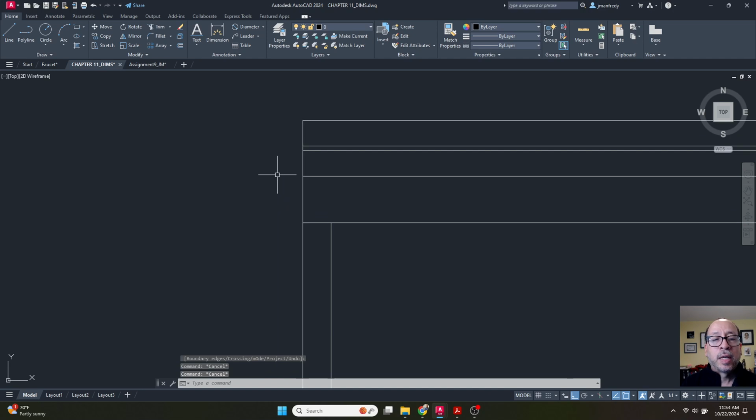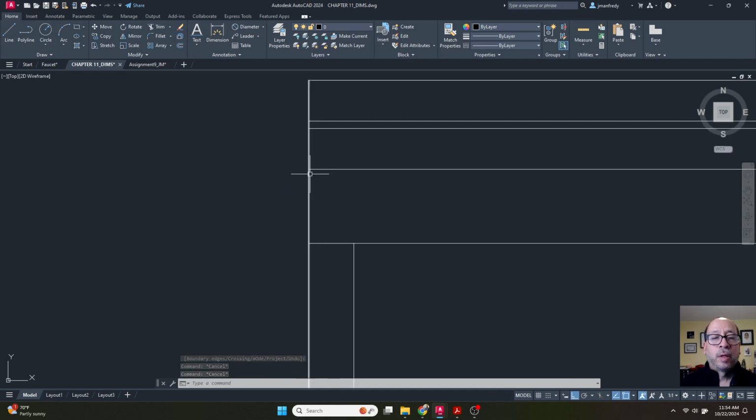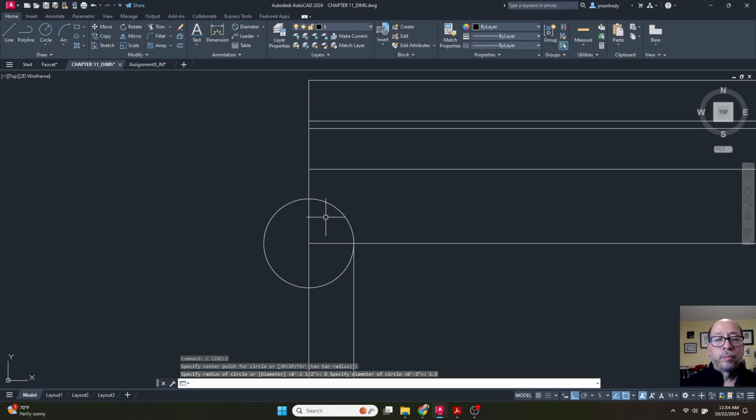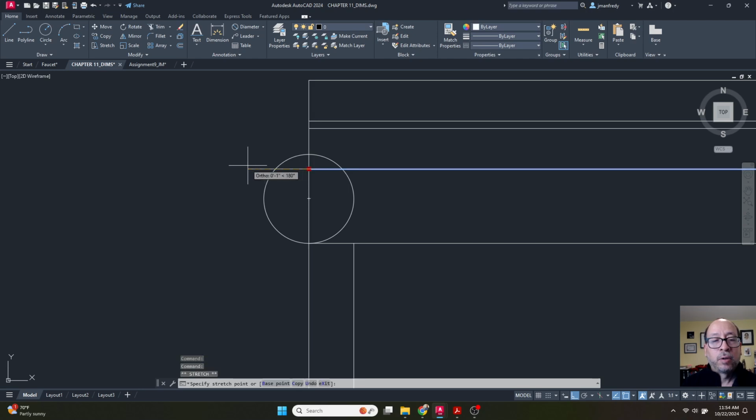And so this has a couple of parts here. There's a couple curves here. One curve they're saying is 3/4 of an inch. So I'm going to draw a circle here. Diameter D, and I'm sorry, the radius. Diameter would be 1.5 inches, 1.5. And I'll move this from that point to that point there. I'm going to take this and extend it over here.